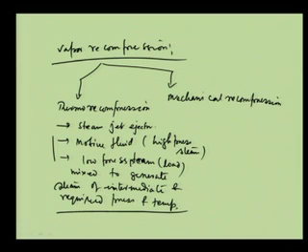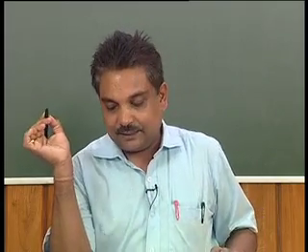The motive fluid is the high pressure steam, an external supply, and the low pressure steam is the load, which is coming from the single effect evaporator. These two are mixed, and the details can be seen from different places, to generate a steam of intermediate characteristics in the form of pressure and temperature, which is then recirculated back to the single effect evaporator.